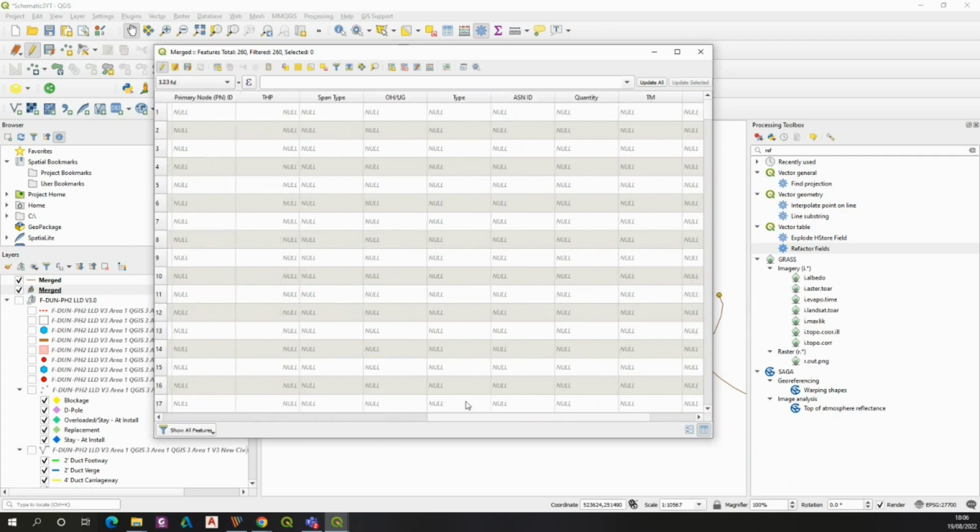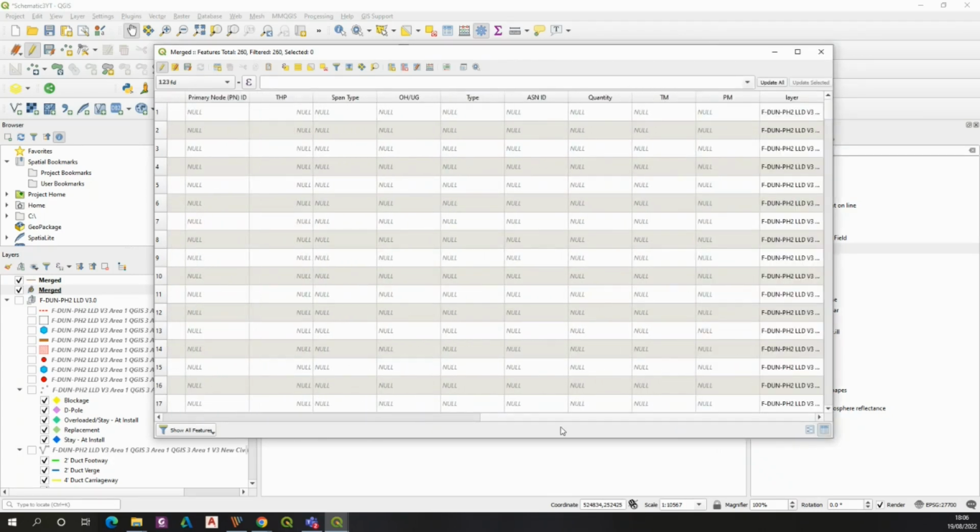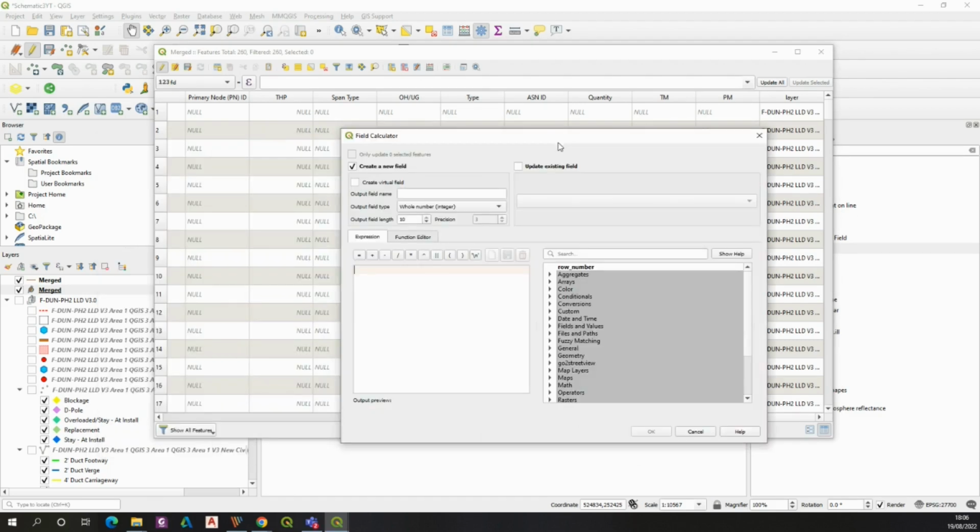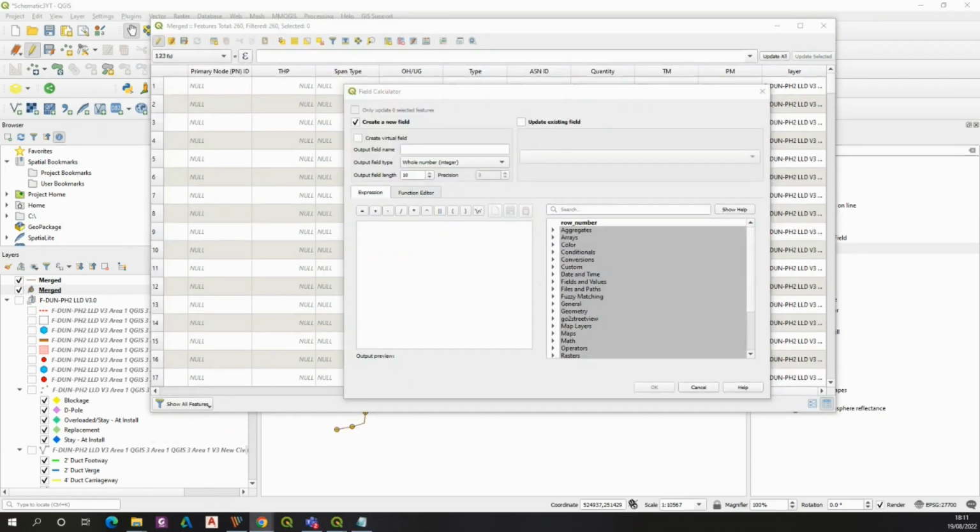Alright. So let's consider this layer name is quite protracted from my point of view, so we need to find some solution in order to keep it more simple. Like you see, I believe we won't need this first part of the string at all. So with this help, we can use the field calculator and use the function which will replace the string with the other one. In practice, we'll replace our part of the string with nothing. So let me do it right now. So as I said, there is a function, not regex replace, simply replace, which will supersede our string with anything we want. In my case, with nothing.